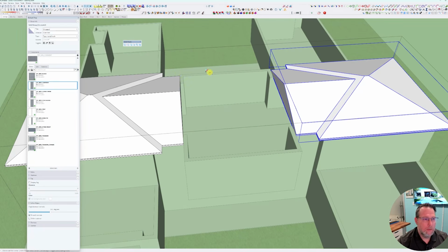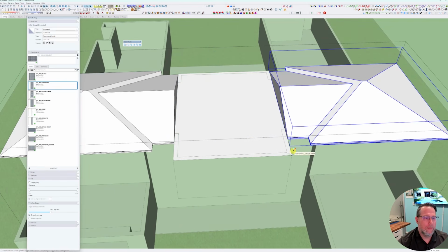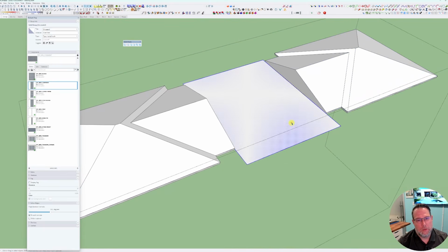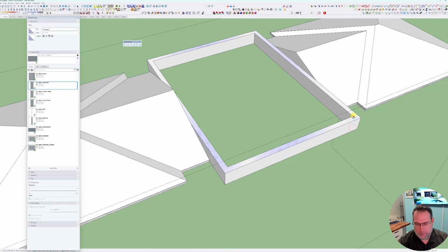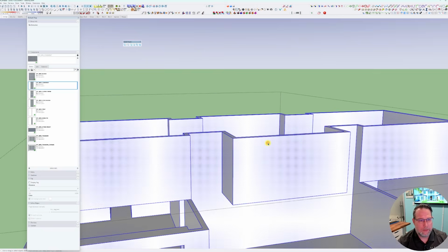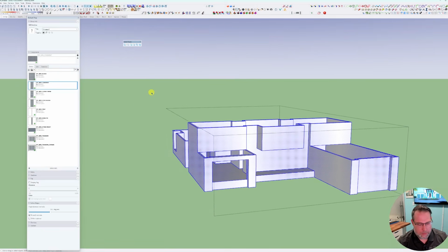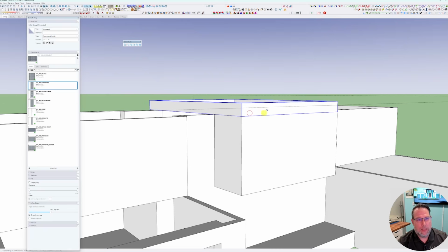So the middle piece, why we didn't do that one, is because I'm actually going to do a pop-up roof here. So I drew the rectangle. I'm going to offset this again 10 inches, delete the interior, and I'm going to push-pull this up 24 inches because I want to create a 24-inch beam change. I'm going to turn that into a group, Control X. I'm going to come back out, and going into my wall group, select all, Control G to turn that into a group, Control Shift V to paste that in place. And now I can outer shell these guys together.